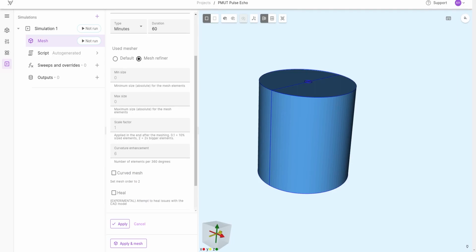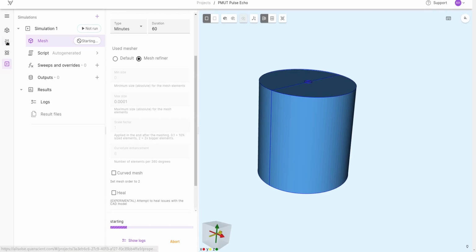1 megahertz, a sine square pulse of 1 megahertz. So that's the most powerful harmonic of the drive. And then what's the mesh size going to be? Well, you have to tune it in a way that you capture accurately enough the highest frequency you want to capture. So let's see with this in water. So you can calculate this, but in water it's 1480 meters per second propagation speed.